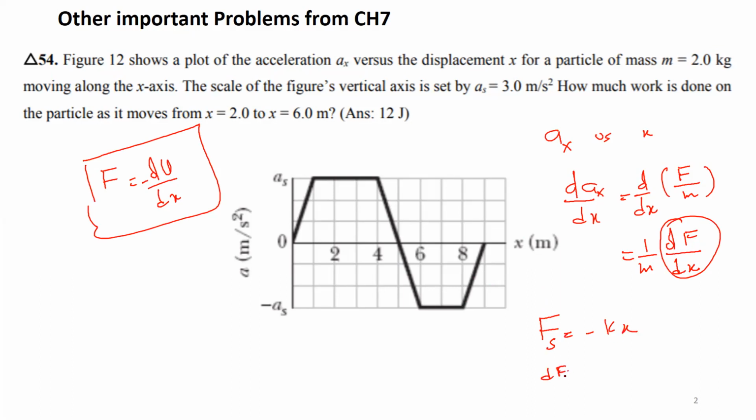What is the derivative of Fs with respect to x? Minus k. So this derivative is a kind of modulus of elasticity. It's a kind of spring constant. It shows you how stiff your system is. It's proportional to the modulus of elasticity.